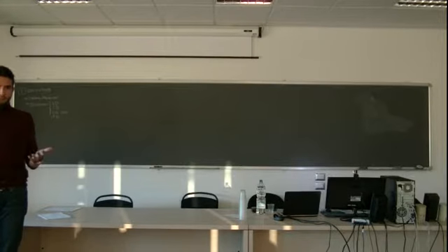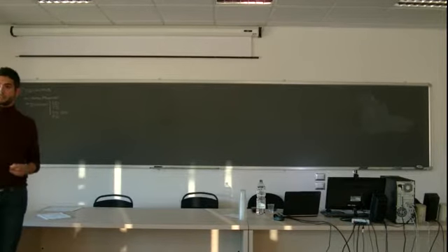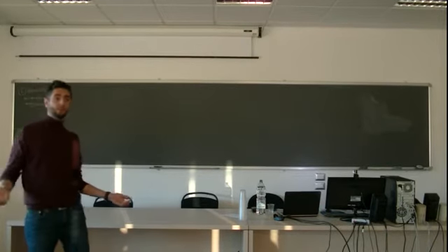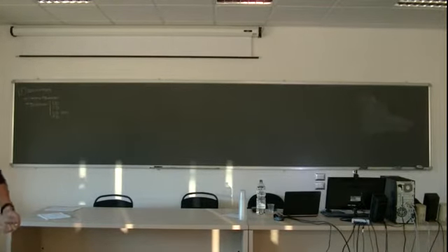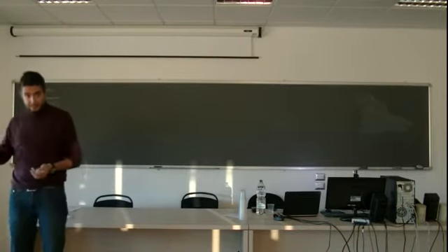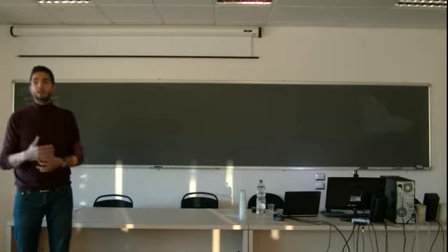Ask yourself how complex you want to have the numerical model. Usually building walls are 1D problems. Energy Plus uses 1D models for each part of a building envelope, and it works. Like if I want to model the floor, I can use 1D, and some of you can say, yes, but in some hours, sunlight is facing just this area and not that area. Okay, you're right. Is this having a high influence? Ask yourself, I don't know. But what are you exploring?